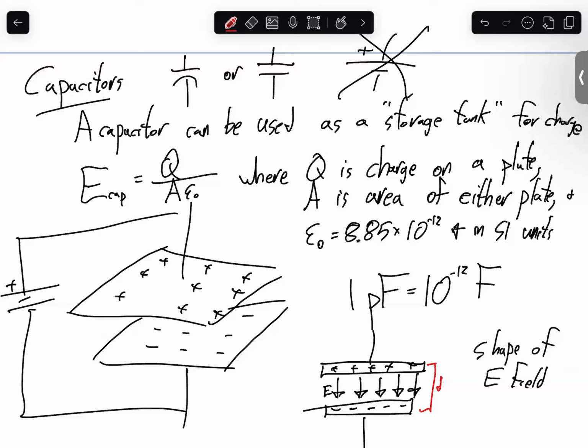If I were to take a voltmeter, put one probe on one side and one on the other, there will be a drop in voltage. The voltmeter would read a negative number if I measure this terminal relative to that terminal. If you reference common here, and measure the voltage here, it will be a negative number. Switches.